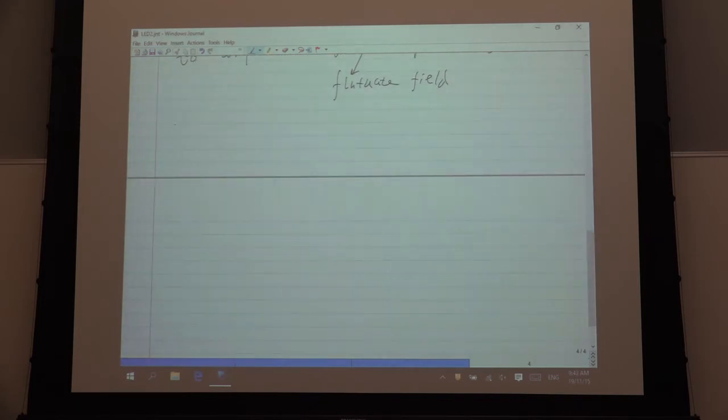One example is Johnson noise. Johnson noise was found by Nyquist. It's the same Nyquist as in the Shannon-Nyquist sampling theorem. At that time Nyquist understood this Johnson noise. It is a resistance. This resistance absorbs the electromagnetic wave and produces heat. They have kBT here. Then they also emit an electromagnetic wave similar to a black body. They balance each other.